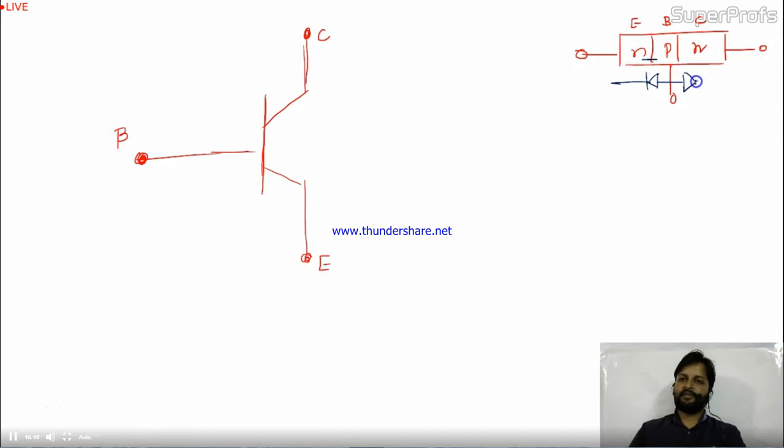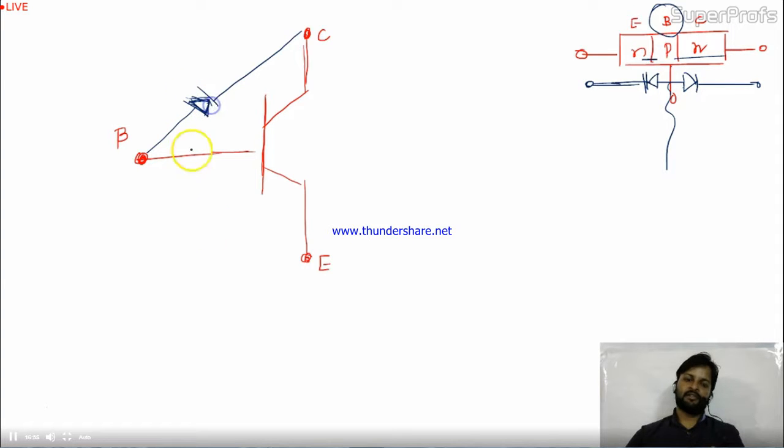This is another diode. It means you have connected two diodes in this way. And in between them, these are the two diodes you have connected, and you are controlling this part. So from base to collector you have one diode, and in this circuit the base is the reference. For NPN, the base is P type and the collector is N type, so the symbol of the diode will look like this only.